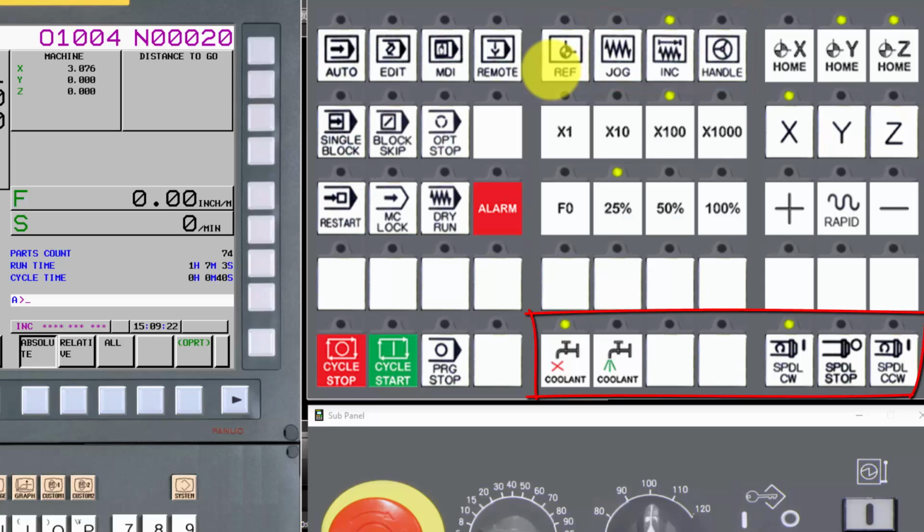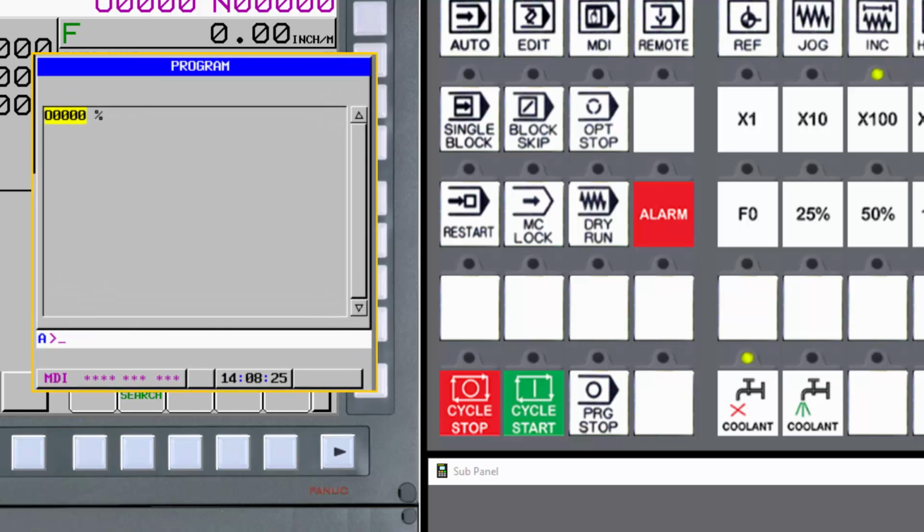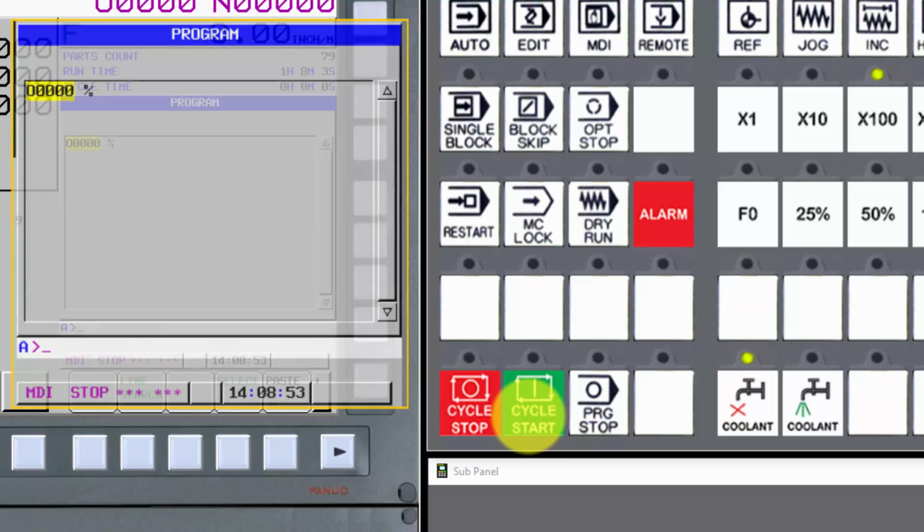This machine operator's panel has a few machine buttons. Coolant can be controlled by M08 and M09, and the lights indicate the active code. If the program code is overridden by manually stopping or starting the coolant, the light flashes to show the manual override condition. The spindle buttons and lights work very similar. Many machine operator panels will have many additional standard and optional push buttons, switches, and lights for a variety of machine features.